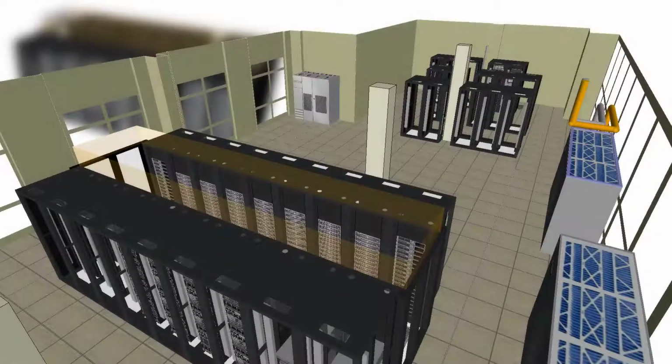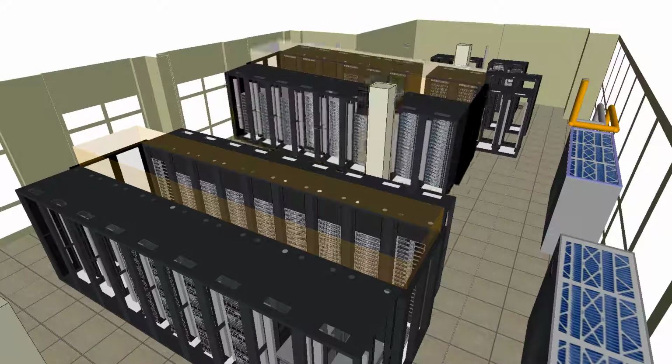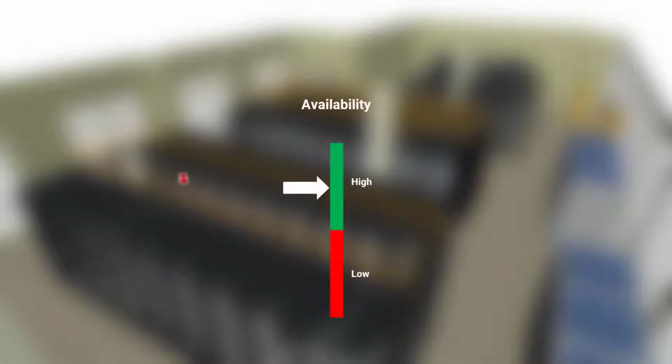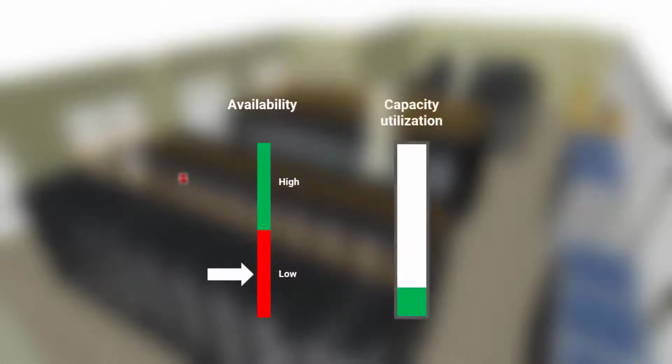After installation, 2 IT units in the adjacent aisle lost cooling capacity and set off their alarms. This behavioral change was overlooked by the prediction. The methods used to predict performance missed this behavioral change, which led to an unexpected performance problem. The risk of a temperature-related failure increased even though the supply of cooling and airflow matched the demand from the IT equipment.